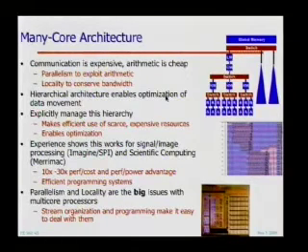If I build a machine that has an explicit memory hierarchy like this, what we call a stream processor, I now can schedule this in a way that makes very efficient use of the scarce resource. I can produce data into a local level of the memory hierarchy and consume it out of there without ever materializing it in the memory system, without ever burning expensive global bandwidth.